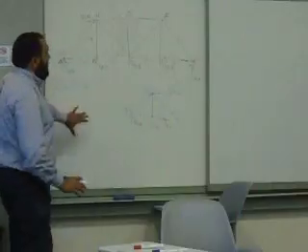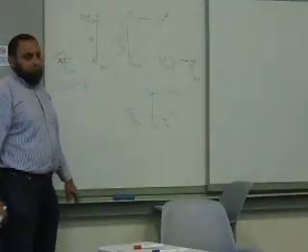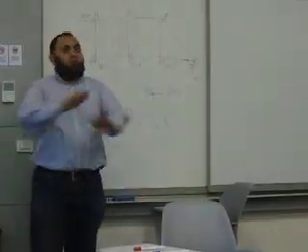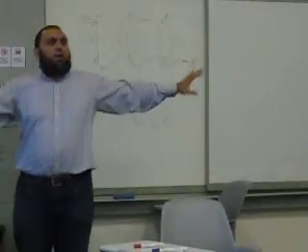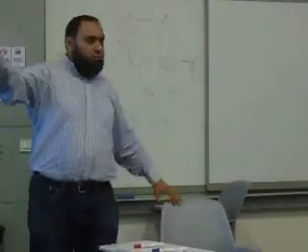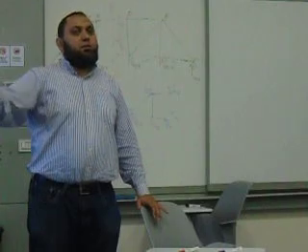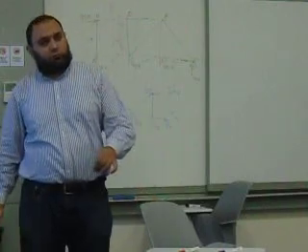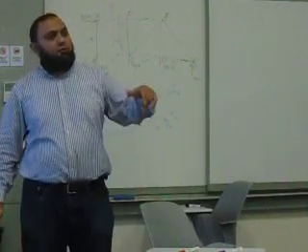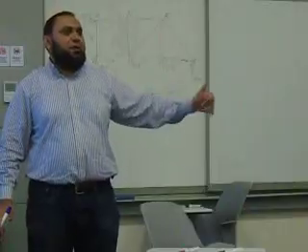starting from here, we will have equilibrium equations. It's a rigid body like any rigid body. So I have sigma Fx equals 0, sigma Fy equals 0, sigma moment equals 0. And the trick is to take the moment at the point at which several unknowns will pass in order to get the other unknown.